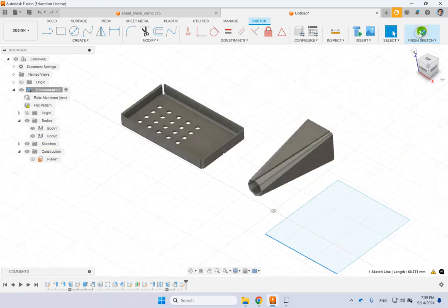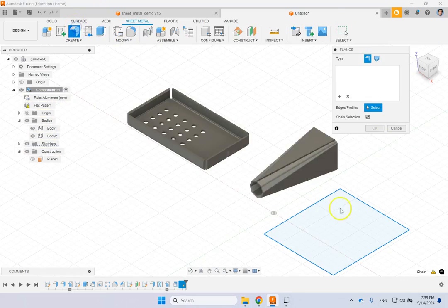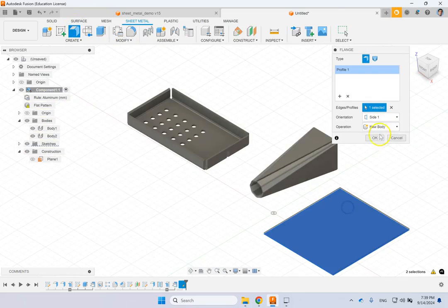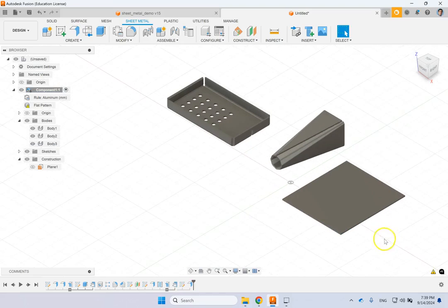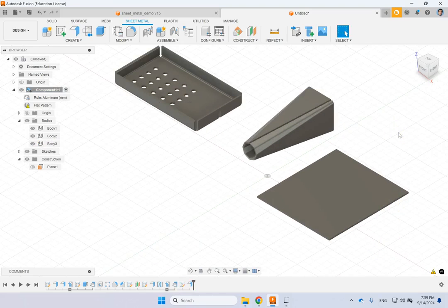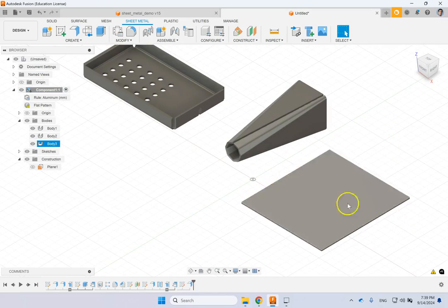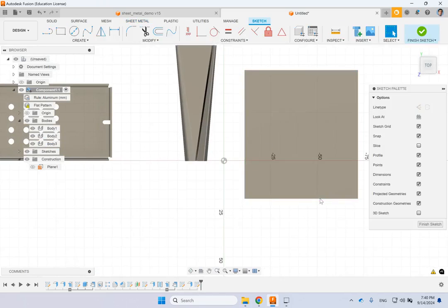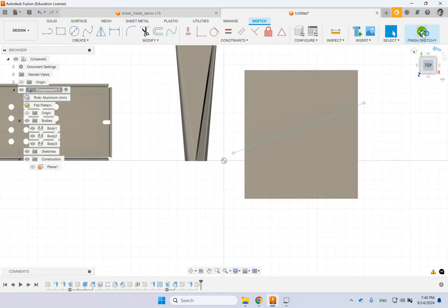And I create a flange out of it. Okay, so now if I want, I can bend it, but anywhere I want along any specific direction. So to do that, I need to sketch off the direction of that line. So I pick the surface. Let's say I want to bend it, but I want to bend it along this diagonal line. Can I do that? Yes.